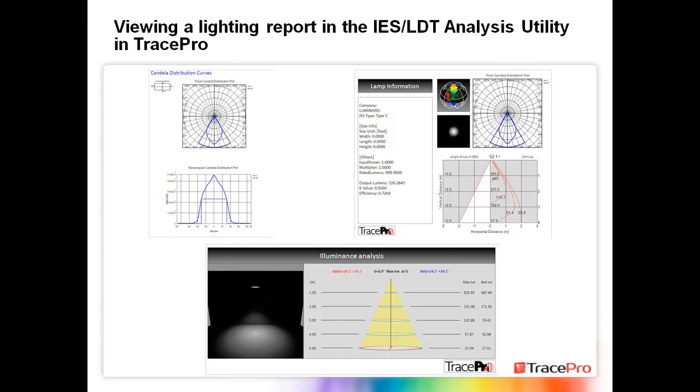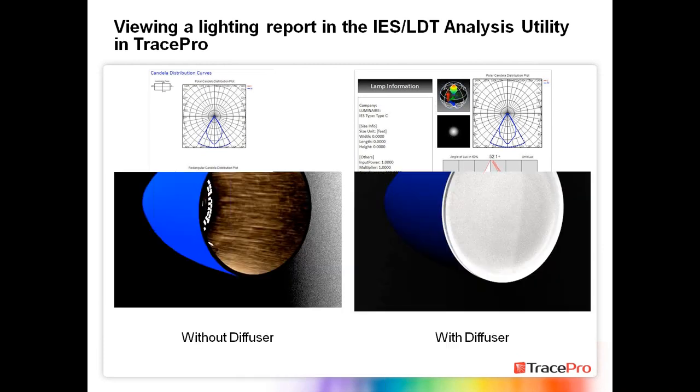And then we can use that to create either an IES or an LDT file that you could then send to another program, whether it's Oxytec's Lightstar 4D, Dialux, or AGi32, architectural lighting programs where you can now take this IES file from this luminaire and insert it into a model environment where you might be modeling the furniture, the wall finishes, the carpeting, and see how it performs there. So these are capabilities we have as well.